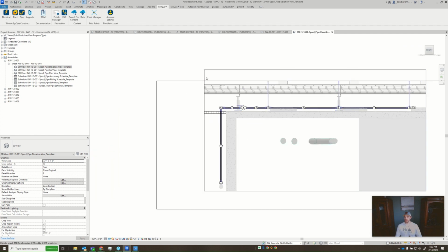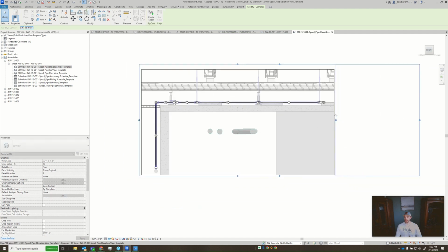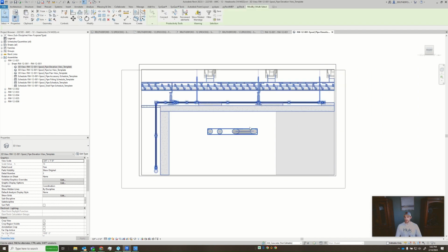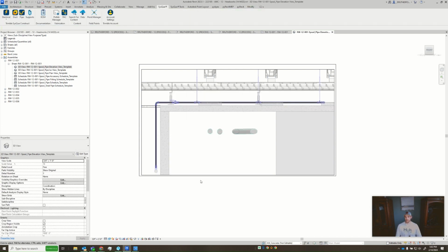So you can see, even though I moved my section out, the crop view does not fit perfectly off the bat. I will adjust that. So now again, select all my tags, filter, check none, tag, tag, tag, apply, okay, and delete. Now, if I'm going to add dimensions here, you will see I'm going to hit DI and I'm going to get a chime. You may not have heard that, but it chimed at me, letting me know that I cannot add dimensions. Why can't I have dimensions? I've already locked the view, it's ready, but there's one key element that we have forgotten. We do not have a working plane to add those dimensions to.